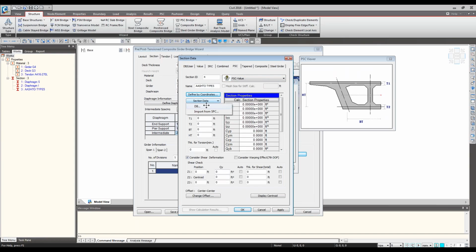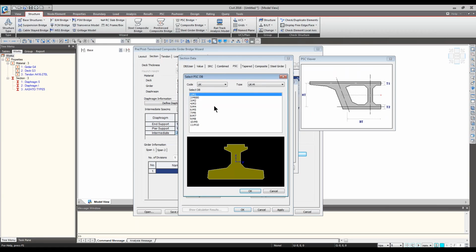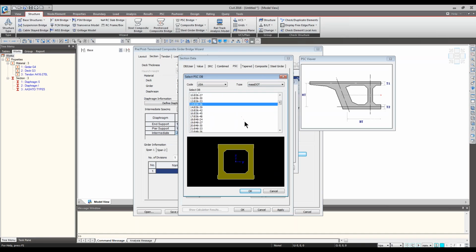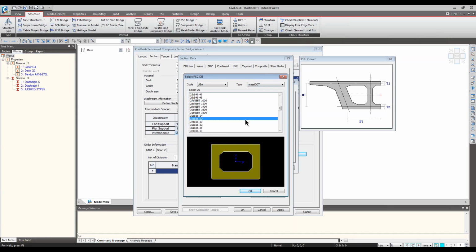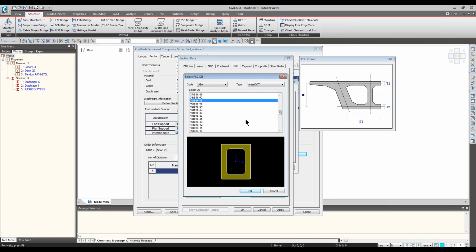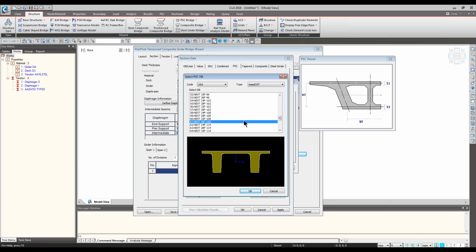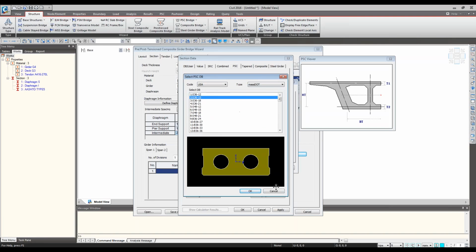You can import the AutoCAD here via the section property calculator tool, or you can simply go to the data again and see over here if we have your database. Massachusetts DOT have quite extensive section database for prestressed concrete applications. So giving you an example, you can bring any of these sections into Midas and use them for this type of application too.